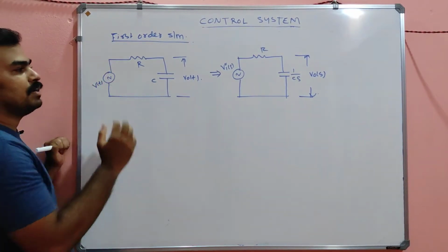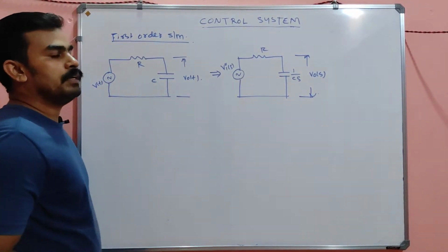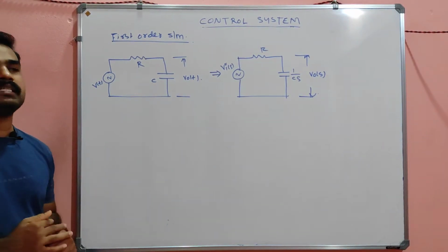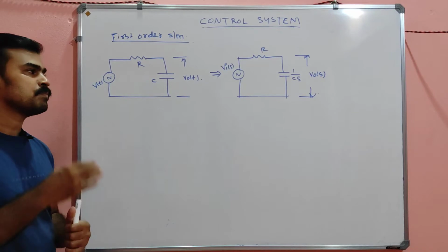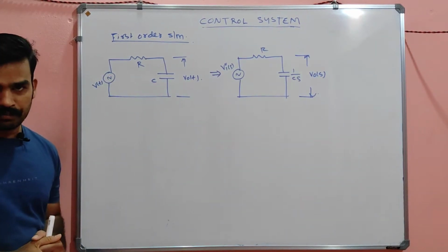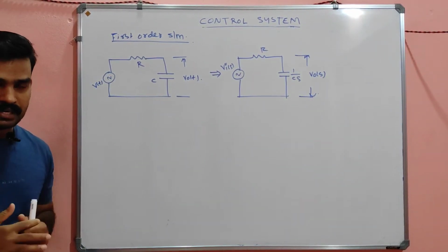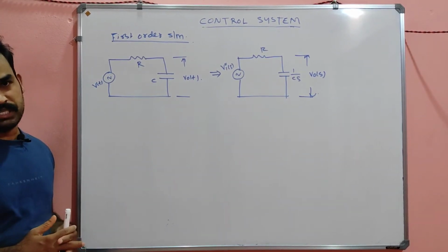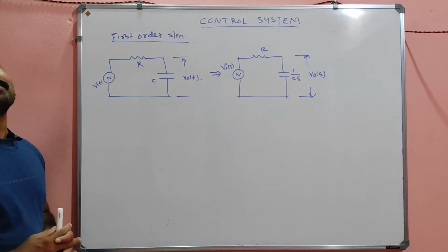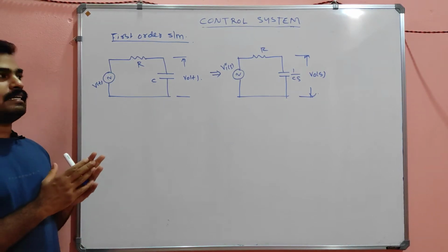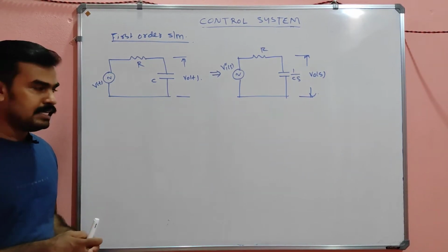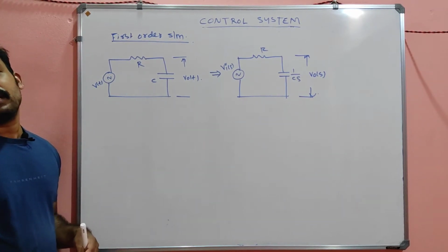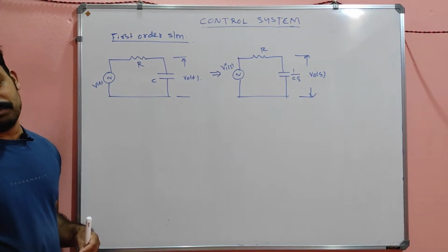So this is a time domain representation, and remember one thing: the analysis of a system and its transfer function is very easily carried out by the Laplace transform. So please convert any time domain quantity into the S domain, because it is very easy to analyze the stability of the system. If you know the things in the S domain, it's very easy to find the transfer function. If you know the transfer function, many things can be learned.